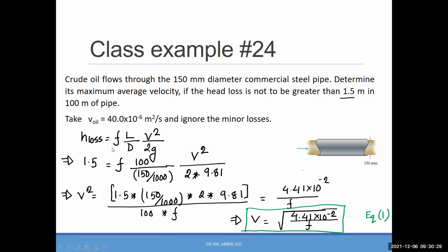And that is a very good question. I got that question a lot during tests, like how can I use the energy equation. So that is the answer. If you know the total setup, whether it was open to atmosphere or not, whether it was a big reservoir or not, that means if you know the pressure and velocity and the elevation at the starting point and the end point, you can apply the energy equation. If not, you will just start from this point. Okay, does that answer your question?